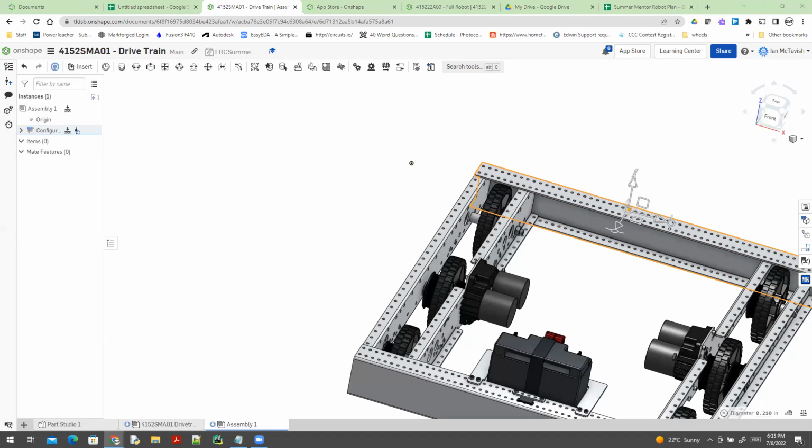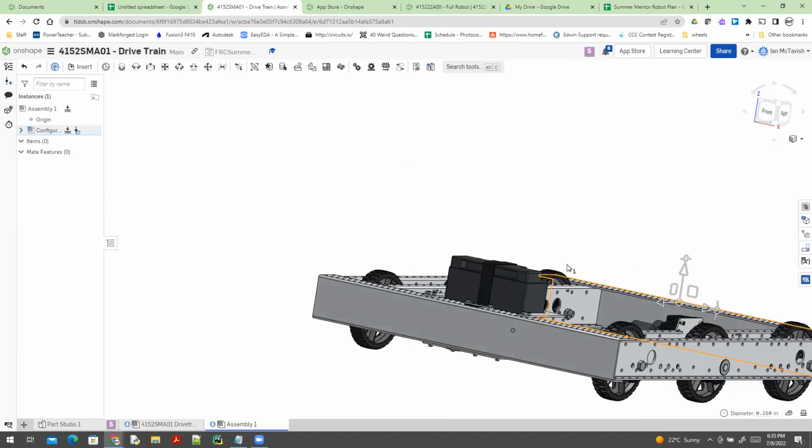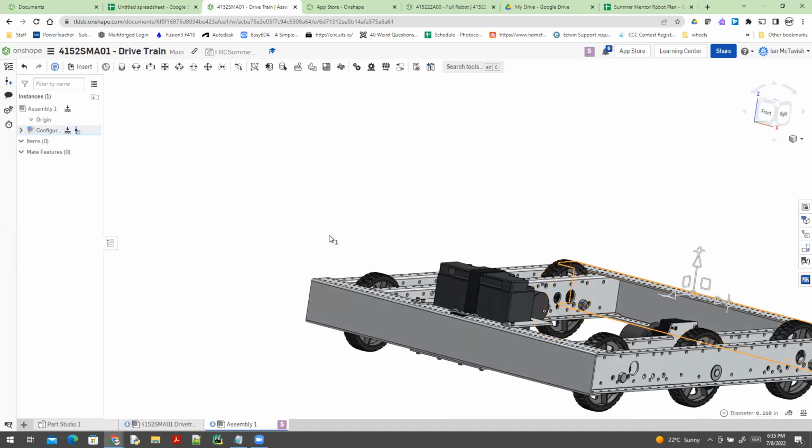And the reason is that the design is so dependent on the center of gravity of your robot. And if you are using different mechanisms, your center of gravity is going to be different. So the climber might not work based on that. So those are things that you don't think about. And so when you're setting up, if you can position it so that it's directly on, that way you can check your center of gravity and know if things are working. Anyways, there is my drivetrain done.